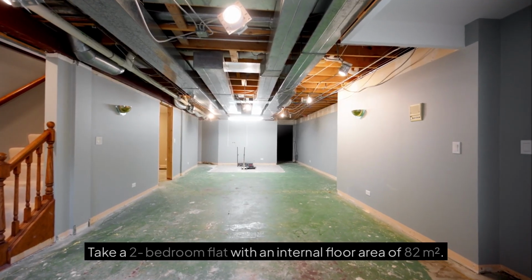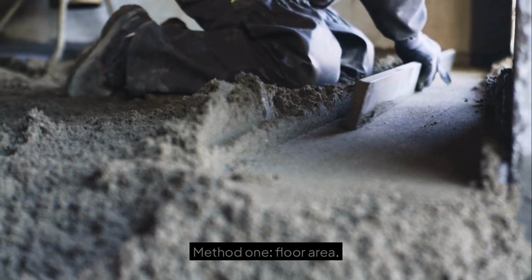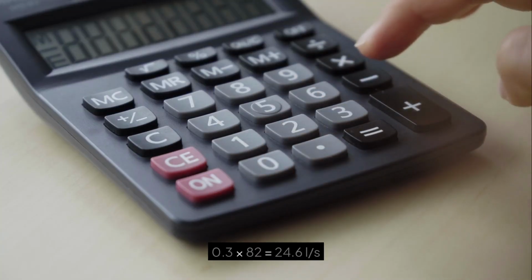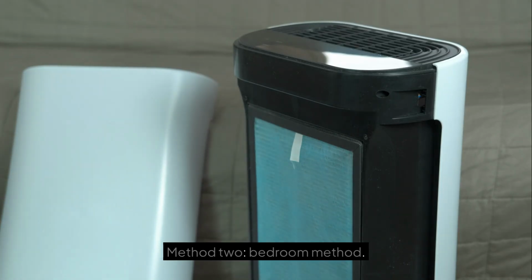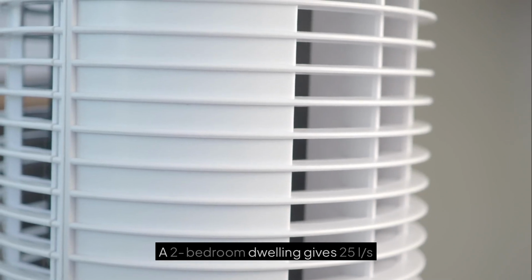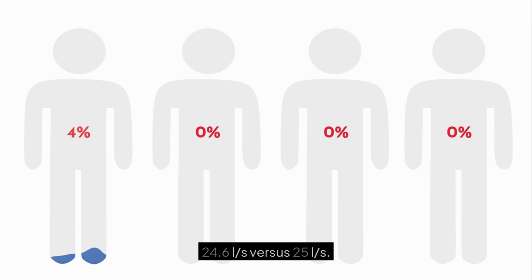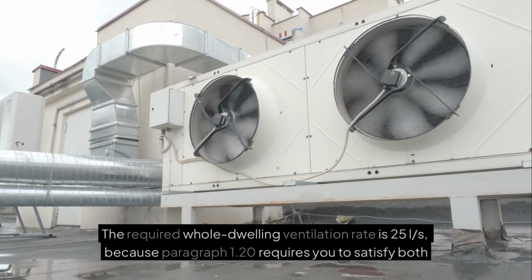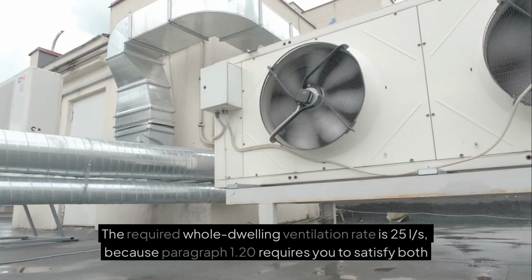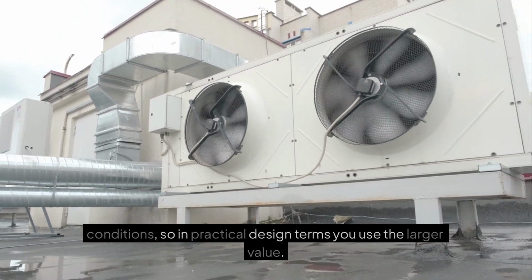Take a 2-bedroom flat with an internal floor area of 82 square meters. Method 1, floor area. 0.3 times 82 equals 24.6 liters per second. Method 2, bedroom method. A 2-bedroom dwelling gives 25 liters per second. Now compare the two. 24.6 liters per second versus 25 liters per second. The required whole dwelling ventilation rate is 25 liters per second because paragraph 1.20 requires you to satisfy both conditions, so in practical design terms, you use the larger value.